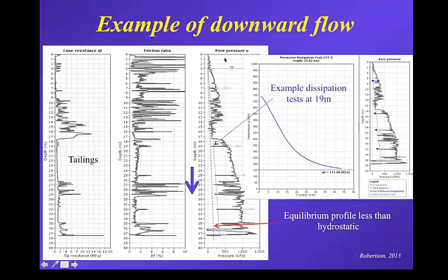If you don't have any sand layers, then sometimes it's useful to stop, say, at the end of the sounding, because you're going to be stopping anyway and getting ready to pull out, and so that's a useful time to maybe spend a few minutes and do a dissipation test to get an idea of what the equilibrium water pressure is like. And I'll talk a little bit about, well, how long does it take?